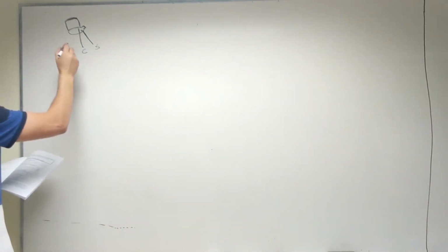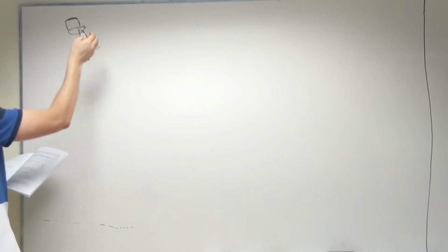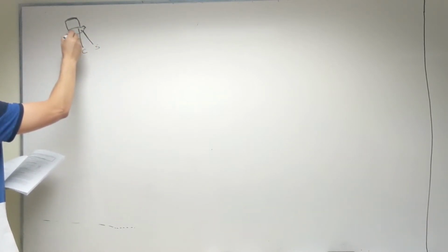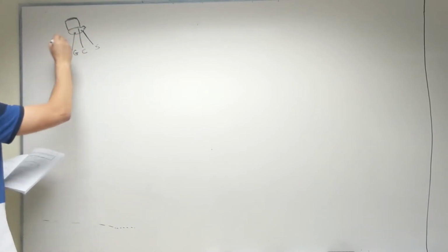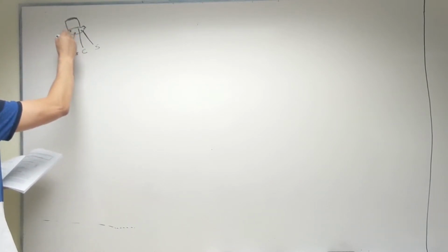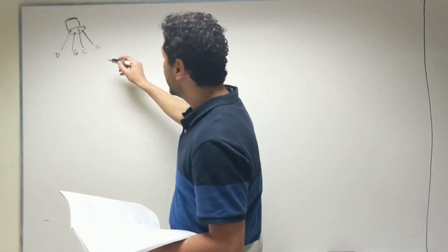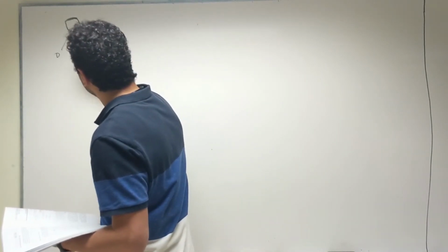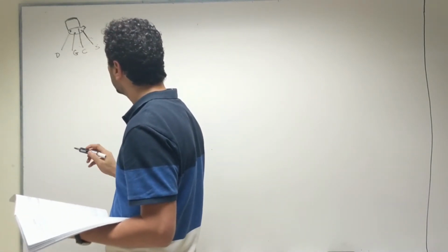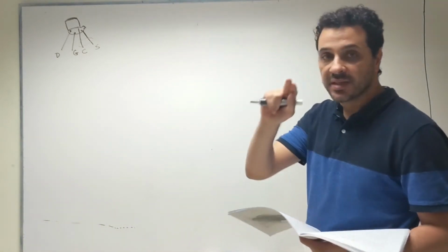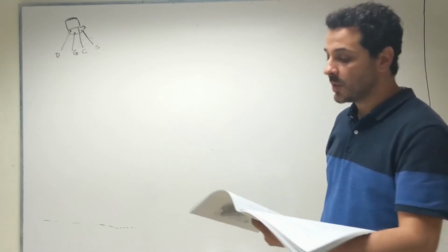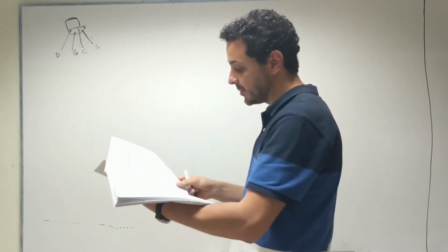And then we have 2 other legs. When we move counterclockwise, we'll find the gate and then the drain. So this is how you will see the device in the lab. Usually the substrate and the body, or the body and the source, are connected together. That's why you will see that they are working as one wire together in the experiment.